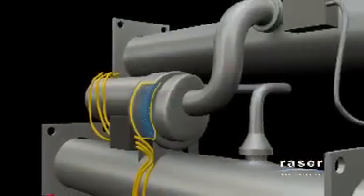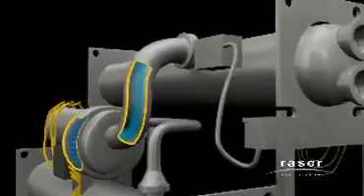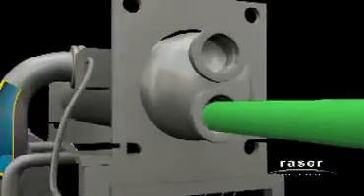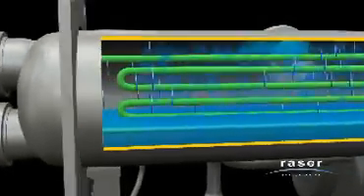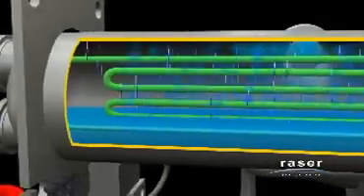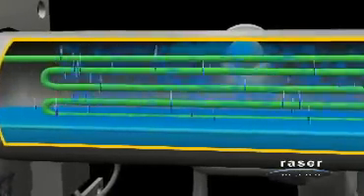After leaving the turbine, the steam moves upward into the condenser tank. Here, cooling water enters the condenser from the cooling towers and circulates through coils in the condenser tank and cools the steam, allowing it to condense back into a fluid collecting at the bottom of the tank. The cooling water enters the tank at about 67 degrees, but after cooling down the working fluid, it leaves the tank at about 87 degrees.